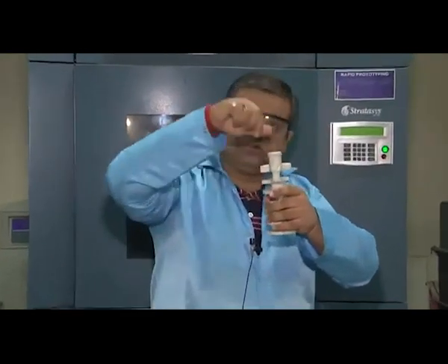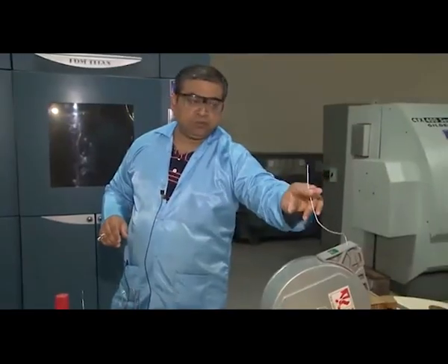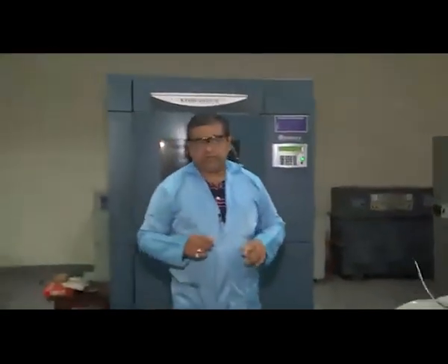So the nozzle would move in that path and maneuver itself by dispensing this particular plastic here by heating it up to its melting point. The nozzle is typically heated at 300 degrees Celsius in this case, so that it melts the plastic, and then the plastic flows across the nozzle, walking across a tool path which is generated into the overall feature size, and it is depositing that layer of 125 microns.